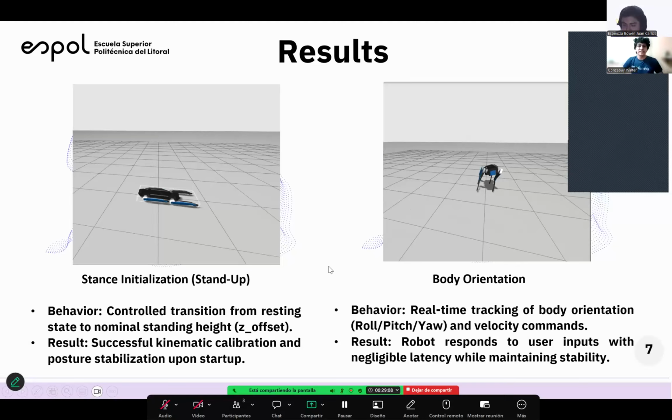In this slide, we present the static control, which is mainly focused on regulating the robot's roll and pitch in a voluntary manner. At this stage, the robot doesn't move, but instead adapts its body orientation based on a given input sequence. The plots clearly show the dynamic behavior of the system, illustrating how roll and pitch evolve over time until reaching the desired reference. We can observe low overshoot and small settling time, which indicates a stable, well-behaved kinematic control response.